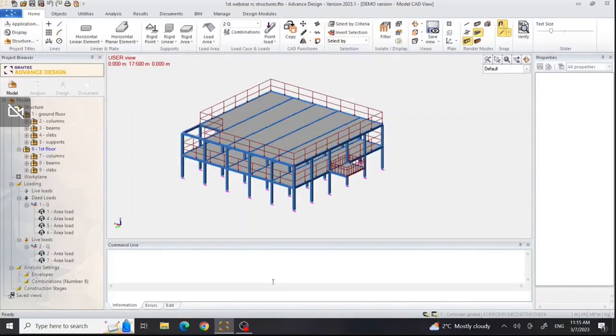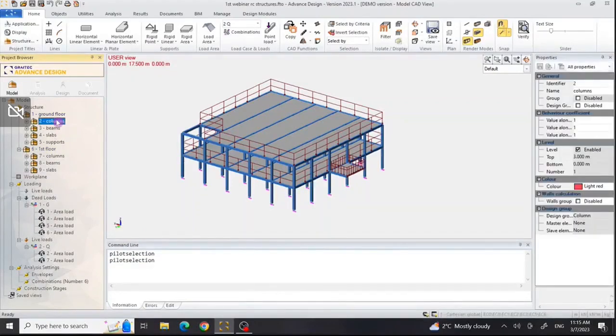Advanced design allows for categorizing your structural elements into different subsystems. These different subsystems can be created based on different criteria, such as the type of elements, different floors, etc. Clicking twice in a subsystem, you can hide it entirely, and clicking twice again can bring it back.